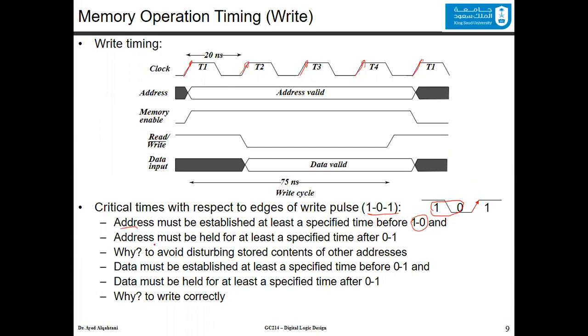Now, it must also be held for at least a specific time after the edge. It needs to be held for some time. Usually we call the time here the setup time, and the time here the hold time. Why do we need this specific timing for the address? To avoid disturbing the stored content of other addresses, and to make sure that we are selecting the address that we want to deal with.